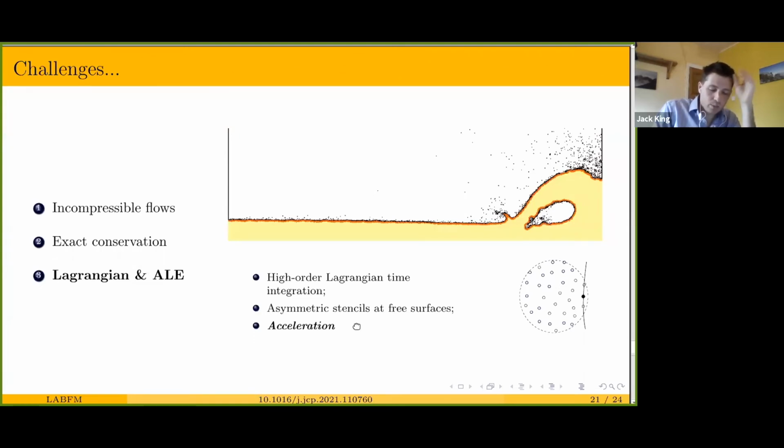matrices. So there's quite a bit of work on other high order mesh-free schemes going on. So there's high order corrected SPH. There's Riemann solver based schemes with Wiener reconstruction, and there's methods like the generalized moving least squares schemes, and they all require some form of polynomial interpolation, and that is going to require solving a linear system for every particle every time it or any of its neighbors moves.